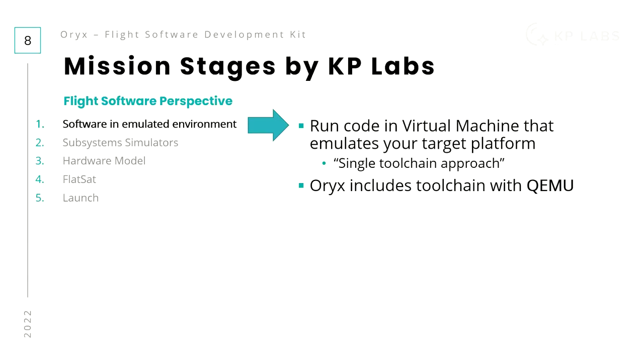However, we don't want to do this because there are errors in toolchains. There are errors in compilers. There are errors in linkers. You could easily misuse them. And the Cortex-M instruction set is totally different from that on your own local machine. There's a different width of the address bus. So there are lots of different things that affect how your software works. And there's no other way actually to test this than to statistically use it as much as possible.